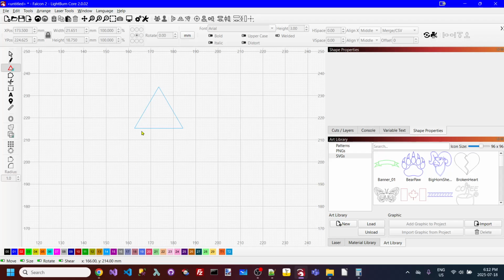Now, I don't want these sharp edges. So another video I did is about corner radius. So I'm going to select my corner radius icon over in the toolbar. Going to set it to 1. And I'm going to add a corner radius at 1 all the way around. Now, when I go into the shape properties, you don't see that corner radius. You do for a rectangle, but not for any other shaped polygon. Okay, so that's the first thing. There's my tile.